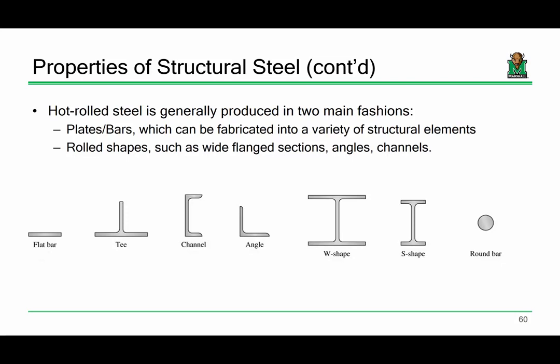Now, we actually don't use I-beams anymore. That seems a little weird when you first hear it, because you say, well, Dr. Mike, that sure looks like an I to me. The reason is that the American Standard I shape we produced back in the day had a very specified cross-section geometry. It had certain slopes on the flanges and whatnot. With modern rolling techniques, we really don't produce that cross-section anymore.